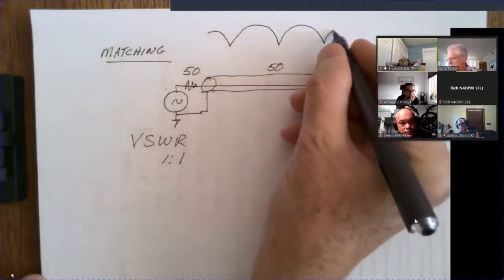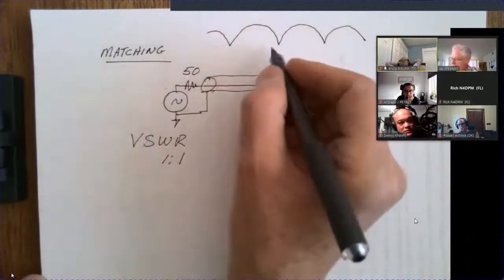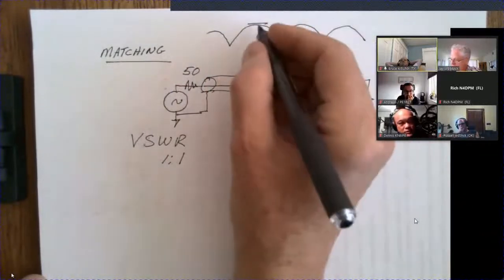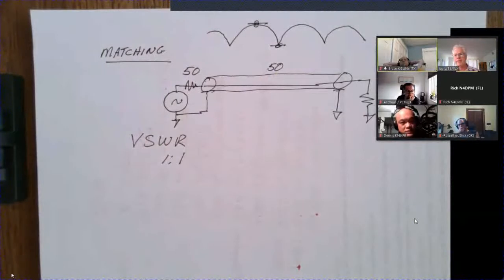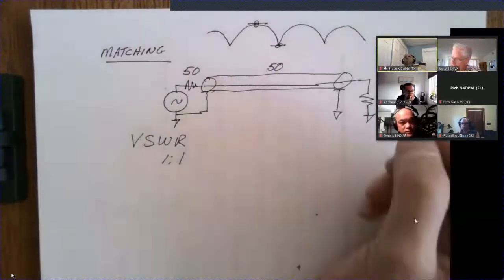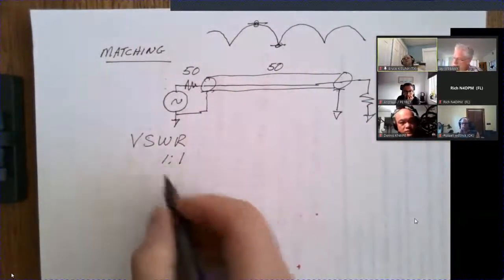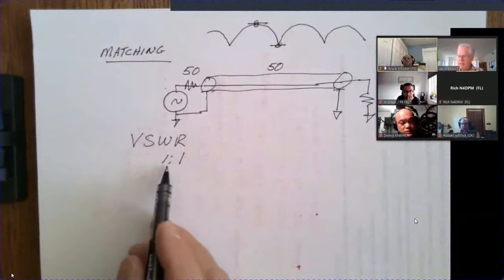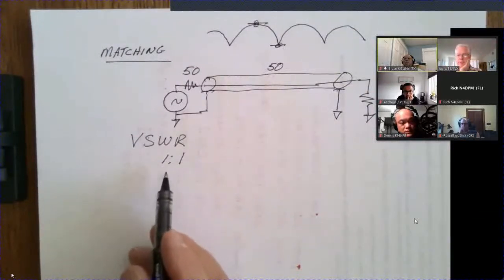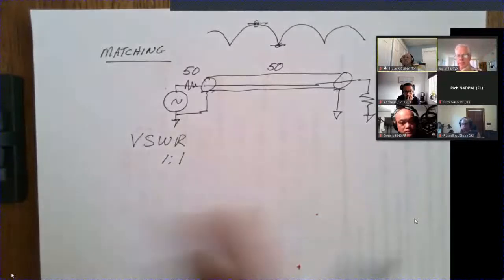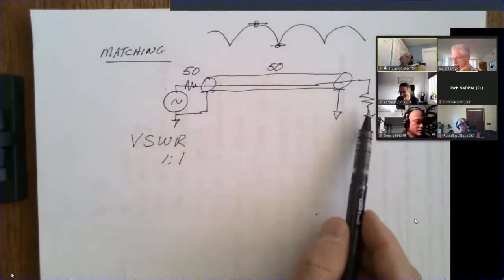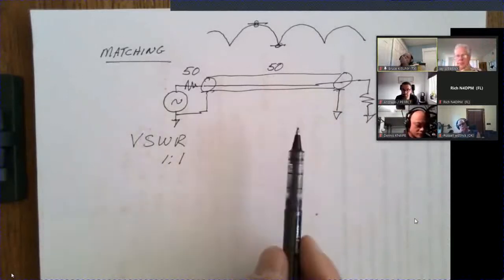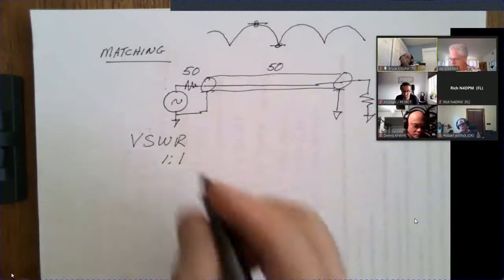And this has to do with reflections and things like that. And the VSWR is the ratio of its peak to minimum voltage. They're not the same, okay? We have meters that measure this for us. They're on your radio, or you can buy meters, you put them in the cable and they will tell you how well your cable is matched to whatever you're talking to.